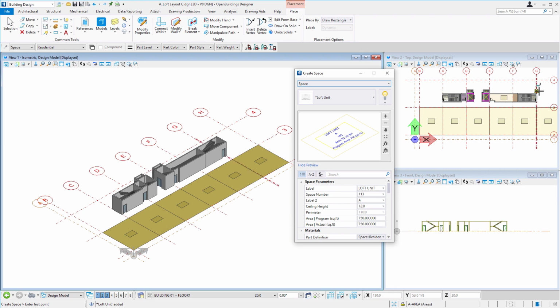B is going to be 550 square feet or 55 square meters, and we need 2 of those. So I think we'll put these on the corners of the building here. And then we need 3 at 350 square feet, rather small units, or 35 square meters. And we're going to put these in these 3 bays here, and we'll leave this area open next to the lift lobby.